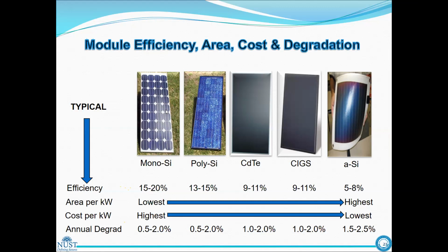What will be the criteria to use the solar panel installation, taking Pakistan as current scenario? Question is very wide. Criteria include different parameters, of course. So first of all, we will consider the temperature range, and then we will consider the peak sun hours for each day.